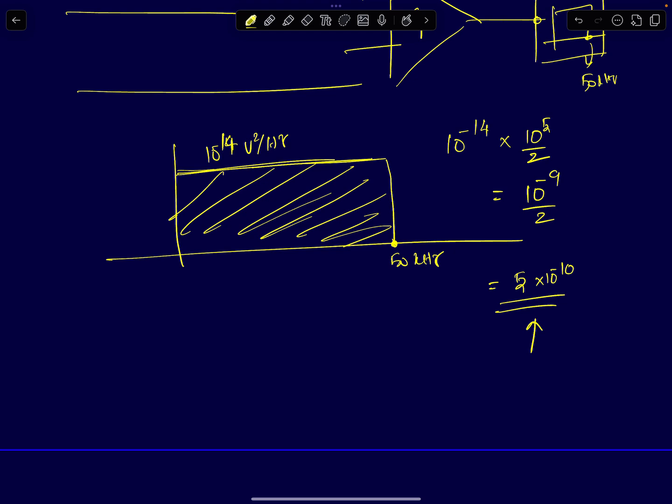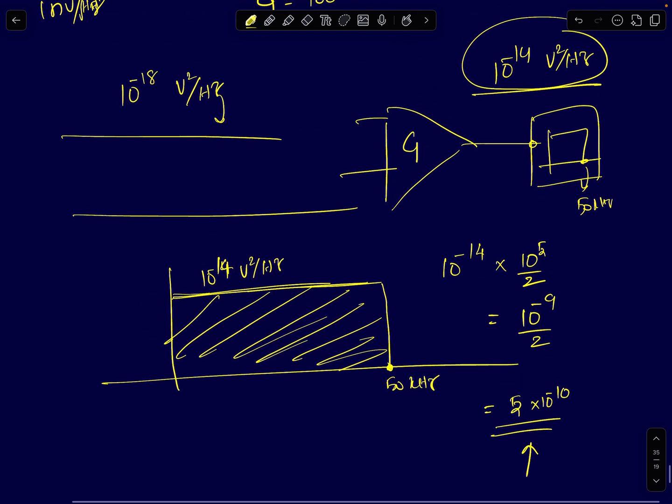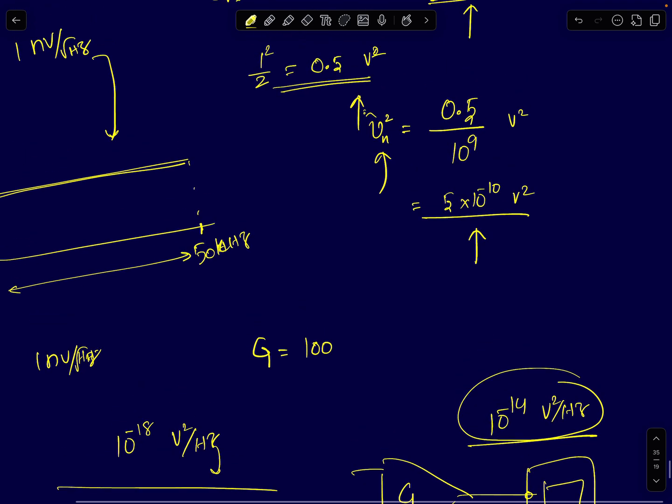Okay, so in this case, if you see, the thermal noise added by your instrumentation amplifier is as high as the input referred noise of your ADC itself. The input referred noise power of the high resolution ADC itself, which still may be okay. It will lead to maybe a 1 bit degradation, half a bit degradation.